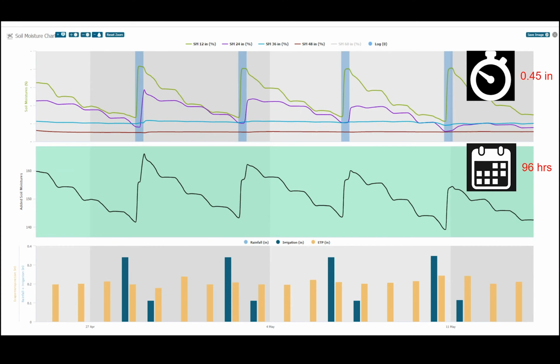I know with half an inch, I fill my tank, and I need to refill it every 96 hours in this case. And that is what varies. That 96 hours is when it's going to change. It depends on weather, and again, the phenology stage, how much the tree is drinking. The 96 hours might be less, might be more, or in certain phenologic stages, you might want to keep the moisture high, so you want to be irrigating more frequently. And then when the fruit is set, or 30 days after the fruit is set, you want to cut back a little bit on the water, and you drop that refill point a little bit.